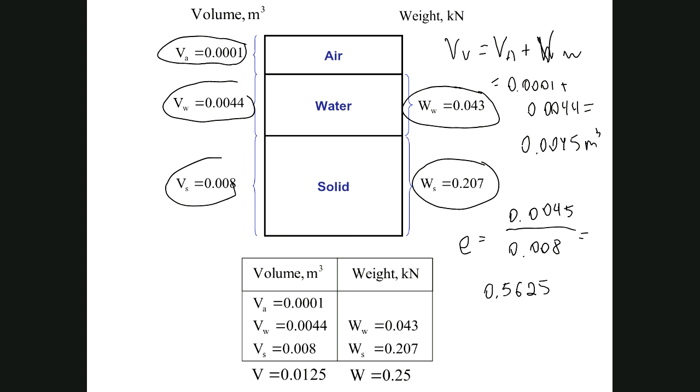So when you present results, just for the future, and also if you don't want to drop any points in your projects, usually for void ratio we have decimal numbers. So in this case we can round to 0.563. So that will be the answer that I will have for void ratio when we present the results. Another important thing is we don't use percentage.